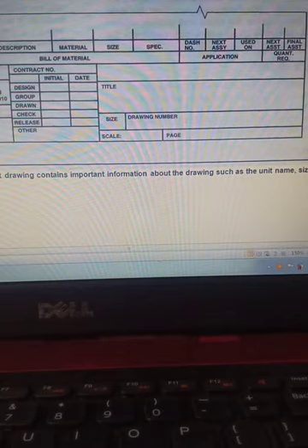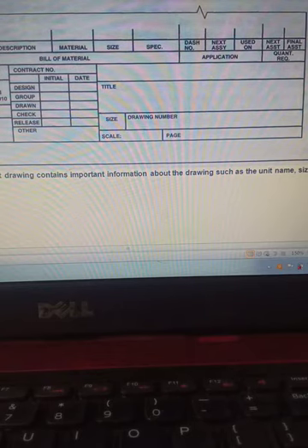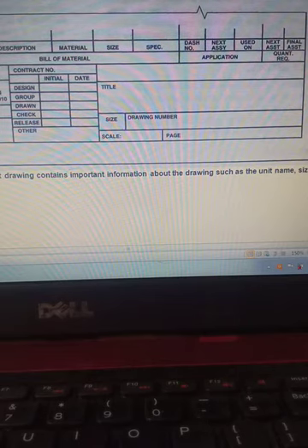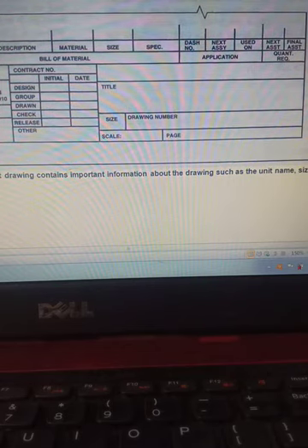Okay, for example, a revision is noted as dimension change in zone C7. You should know that this change is made somewhere in the section 3 feet up from the bottom and 7 feet from the right edge.